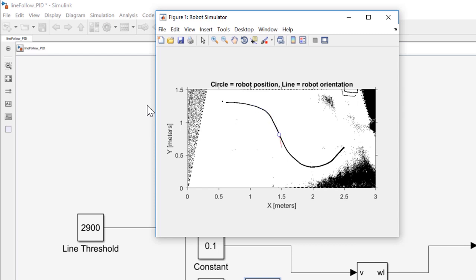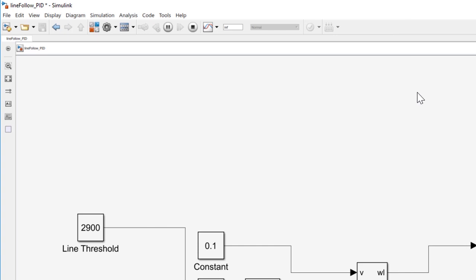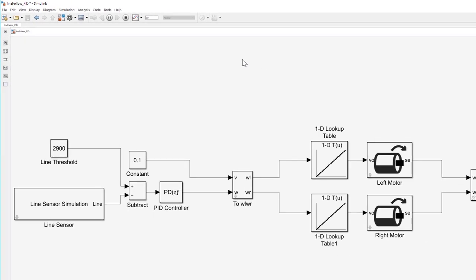It is also interesting to note that using integral controllers for line following is not that popular, because line following doesn't need to depend on all the past error values. In fact, keeping track of the sum of the errors might prove inaccurate and unnecessary for line following, since it will result in the drifting value of the robot. On the other hand, if you only consider the difference in the current and the previous value, you can obtain more accuracy. This is achieved by adding the D controller.